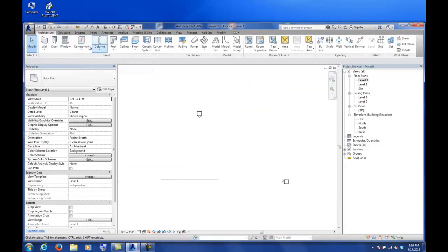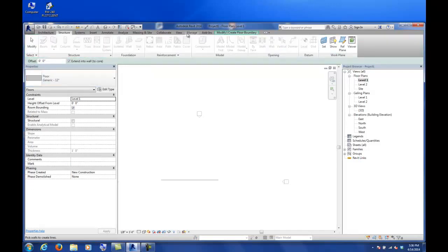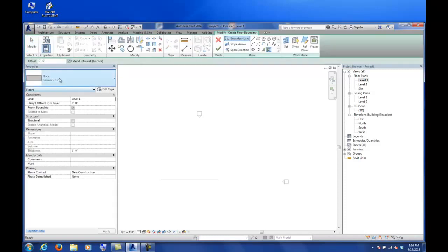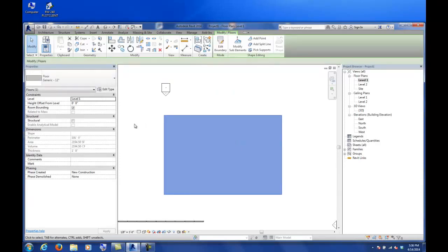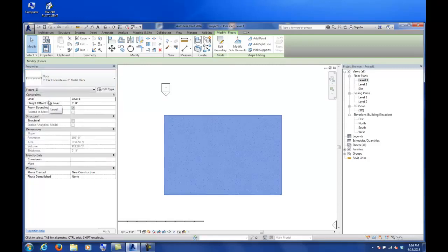So to change your, if you're using a structural, let me close out of that. Right now, our floors are still generic. So what you'll want to do if you have a generic floor, so what's your floor type now? Right now, it's just generic. So I actually have to build the pieces. In our design, it's just steel beams with composite deck on top and a raised floor system on top of that. So you can select your generic floor just like this, and you'll want to pick the one up here called 3-inch lightweight concrete on 2-inch metal deck. Okay. Because this one's set up as a structural composite deck system already.